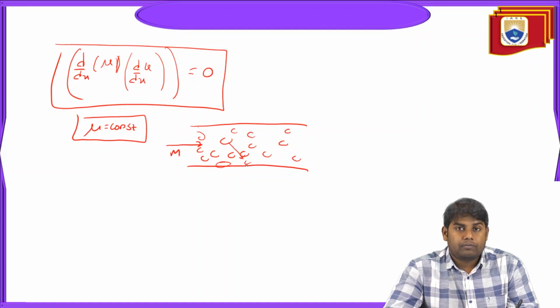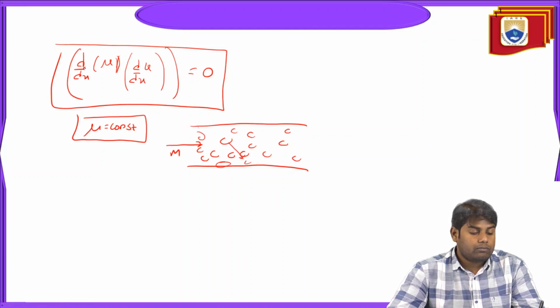So at the wall, the energy is dissipated, which is the small eddy gets damped out. Damped out in the sense, first from the mean flow, the large eddy will take energy. This large eddy will supply the energy to the smallest eddy. This smallest eddy actually dissipates, or let's say gets damped, or it goes into another form of energy at the wall. So the wall temperature or the properties at the wall will change. Okay, so that is why we have seen this eddy.